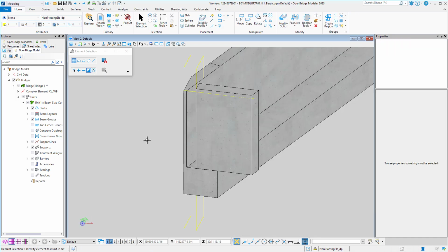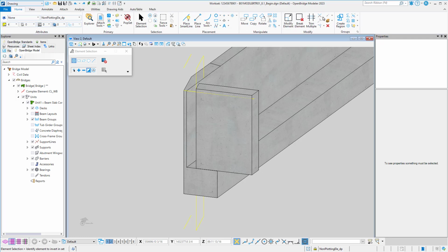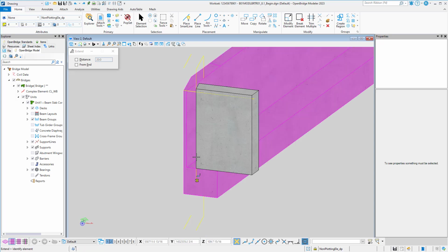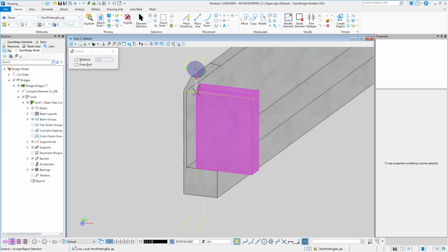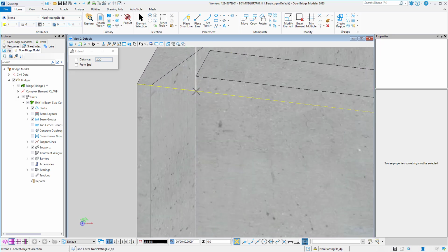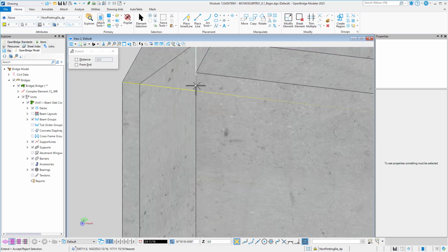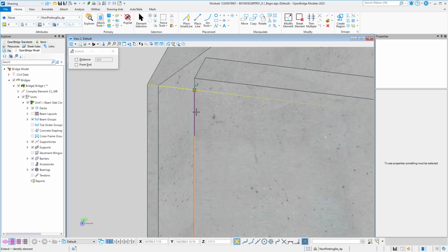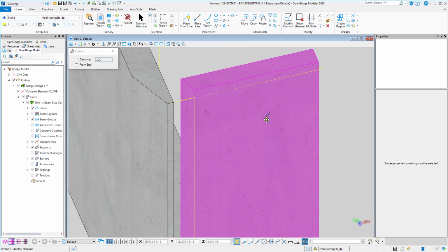We will now do some clever trimming to make sure that the final 3D element we create can properly be united with the end bent. For context, when using the Unite tool, if two of the 3D elements aren't properly touching or within the limits of each other, then you will get many errors. So what you're seeing here is me moving the extrude along path to be well within the end bent cap so that this is not an issue.